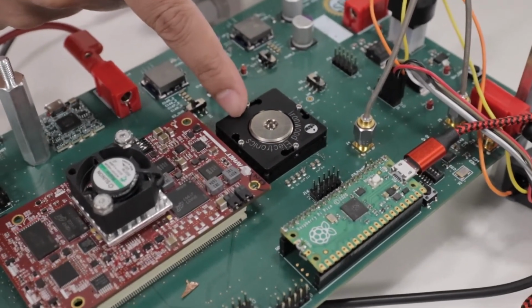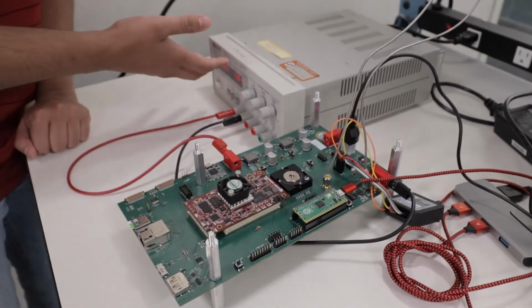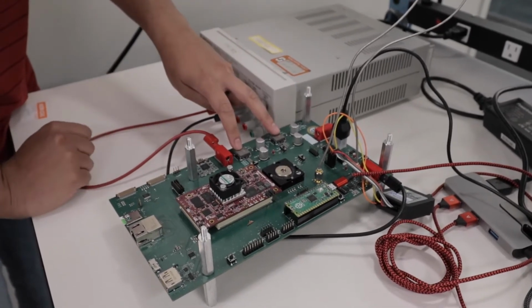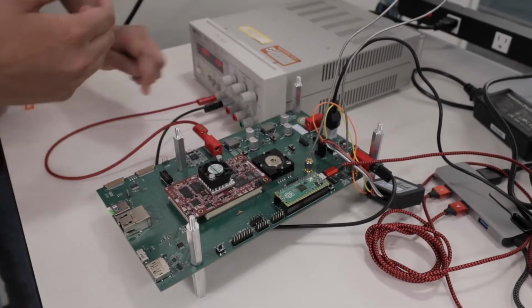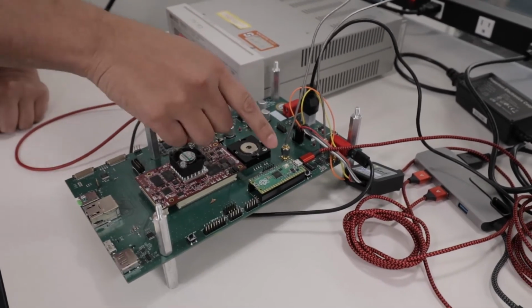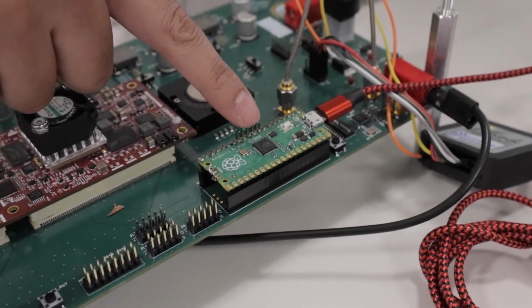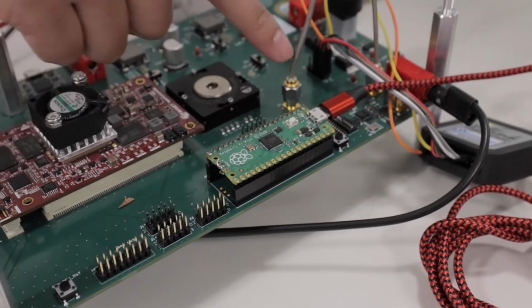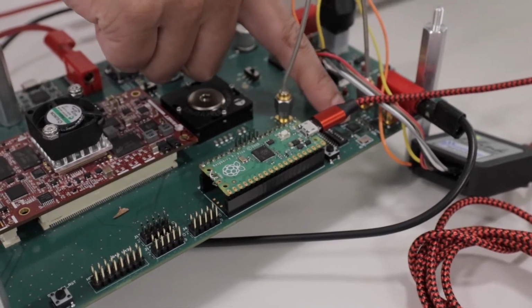This chip is housed in this socket here and can be powered either through the external power supply, which we showed before, or using a 12-volt source, which is broken down into 2 voltages controlled by these 2 power supply modules. We are able to program these power supply modules with the Raspberry Pi here. In addition to being able to program the power supply modules, we can also program the clock that reaches the chip with this clock generator here. This allows us to run applications at different frequencies.